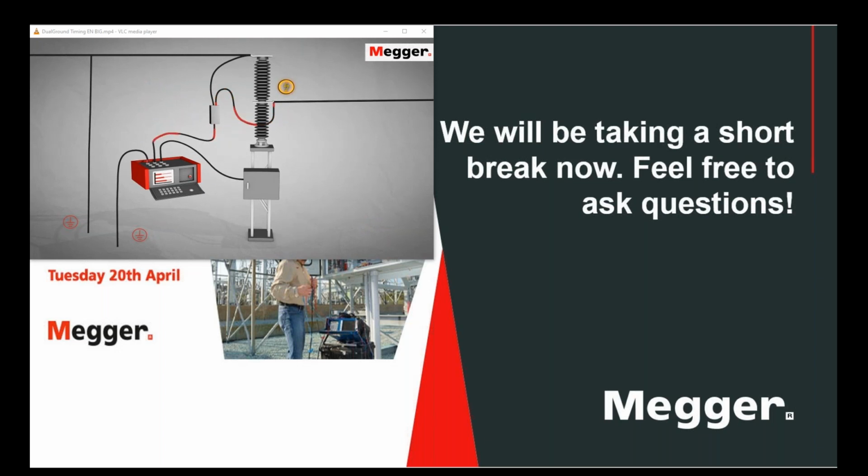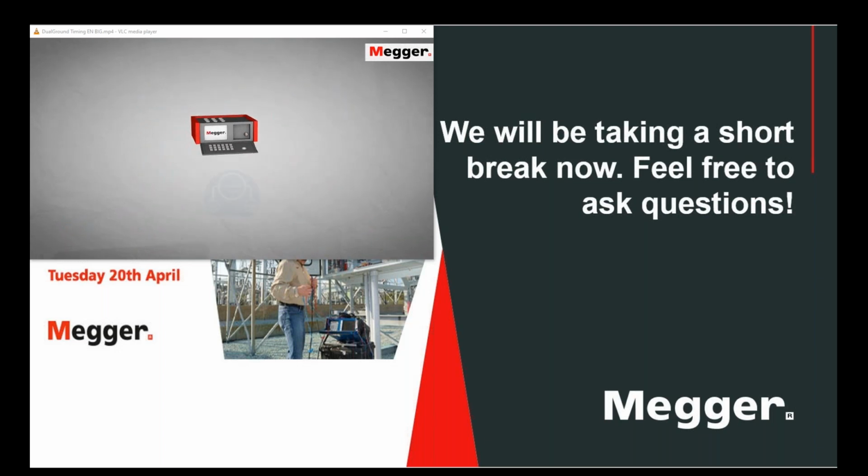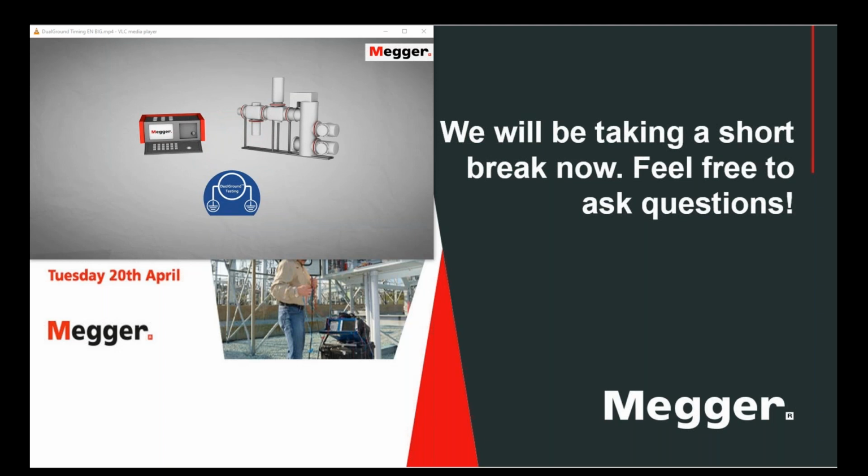which is time-consuming and moreover increases safety risk. When the measurements are done, the ground cable has to be attached again before the measurement cables can be removed. With Megger's dual ground method, the circuit breaker can be timed without removing the ground, which makes the test both safer and faster. With the TM1800 and the dual ground method, you can also time gas-insulated switchgear and generator circuit breakers without removing ground connections.